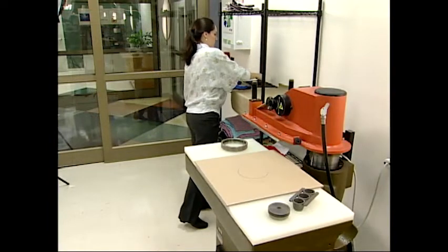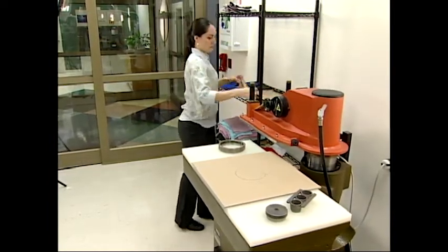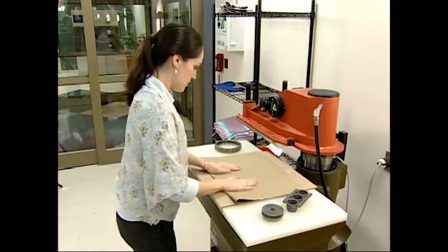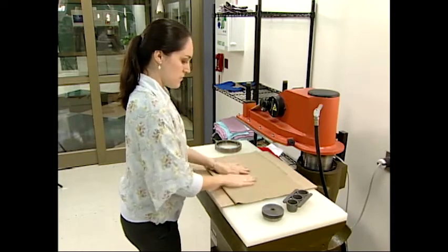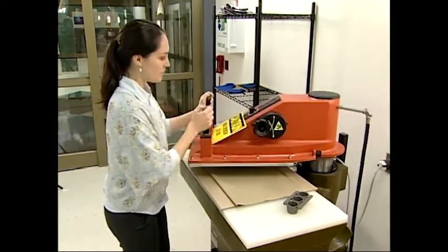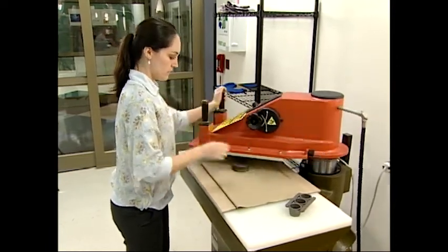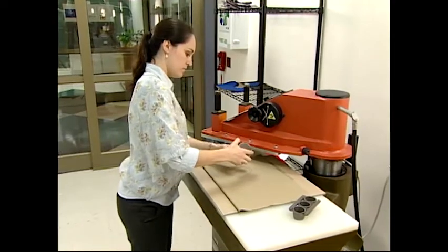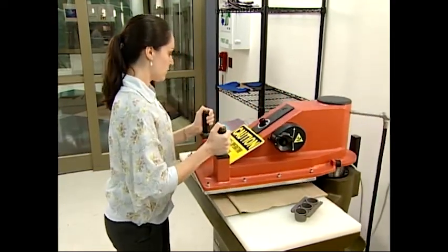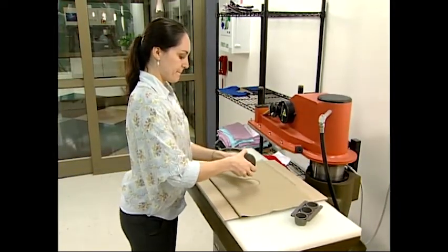Option C allows for determination of weight using a small swatch of fabric. This procedure is applicable when the available amount of fabric is limited. A small swatch of fabric is sent to the laboratory to be used as a test specimen. The results are considered to be applicable to the sample only, and not necessarily to the lot from which the sample was taken. Measurements by this method do not include fabric selvages. Option C should not be used for acceptance sampling due to the small size.